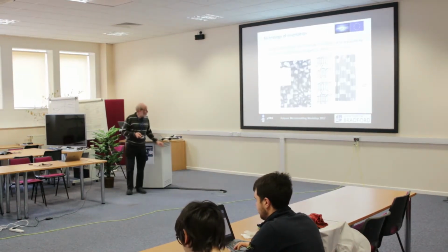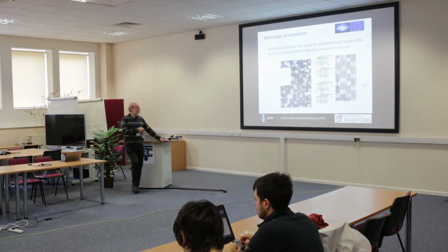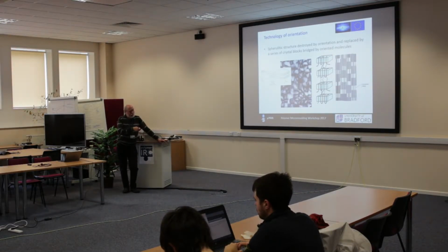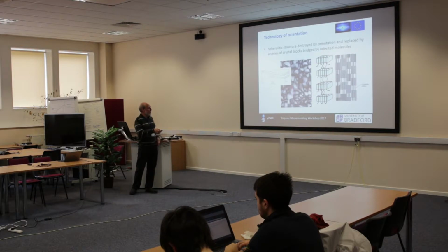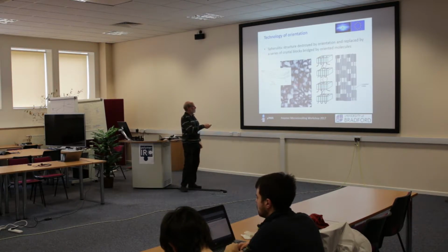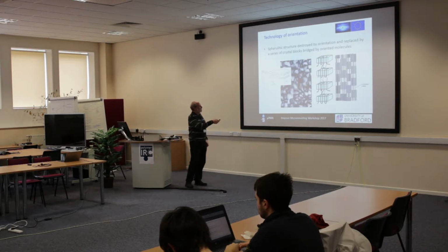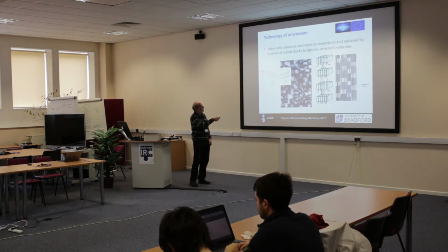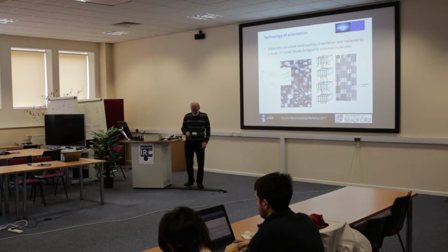So when you draw a crystalline polymer, you may start off with this spherulitic structure, which is because the crystal lamellae nucleate from a point, and they grow away from that central point, and they form sphere-like structures. Here you can just about see the difference in the shade, as these are crystalline and amorphous layers, and these spherulite-type things. So you've got sheets of polymer growing like this, and amorphous material between the sheets.